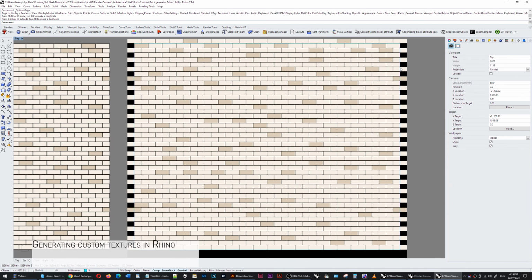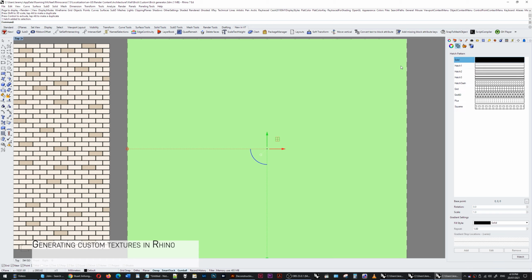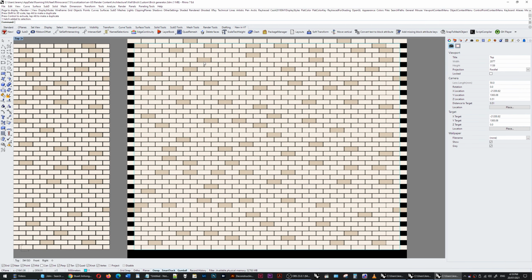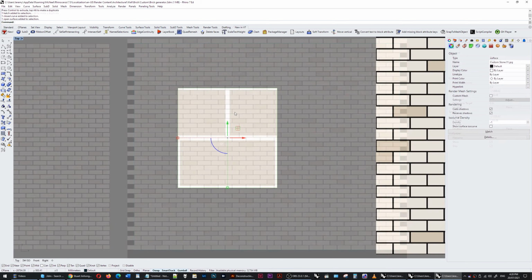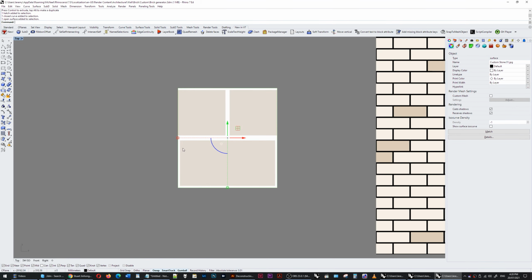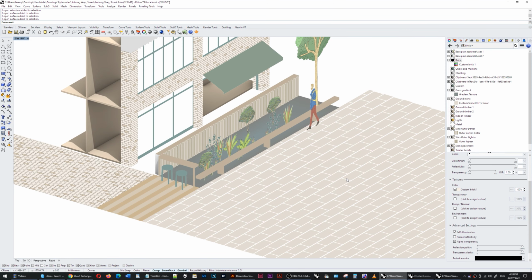For the bricks, I generated them in Rhino using hatches. I created a black hatch background and randomized some darker bricks and some lighter bricks. Both of the brick colors were sampled from the original image, and a percentage of them were selected to be darker. I copied this into Photoshop and cropped it to that blue square and exported it as a JPEG. This JPEG here was a brown tile on white backing, one full at the bottom, two halves to either side at the top, and that means when it's repeated square after square, you get the Flemish Bond appearance.